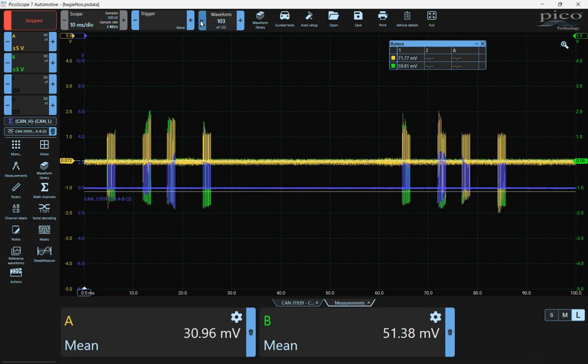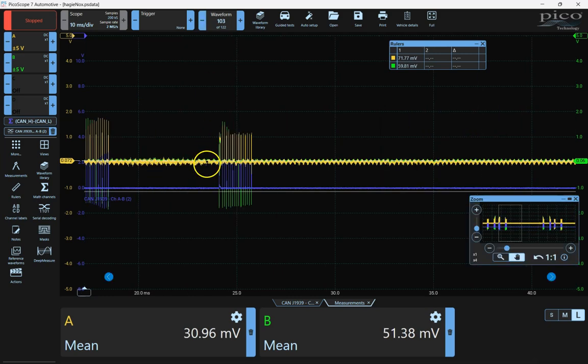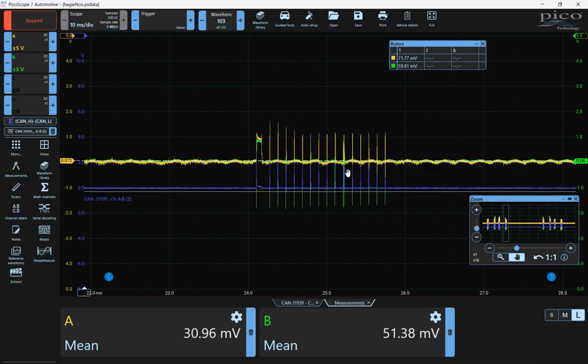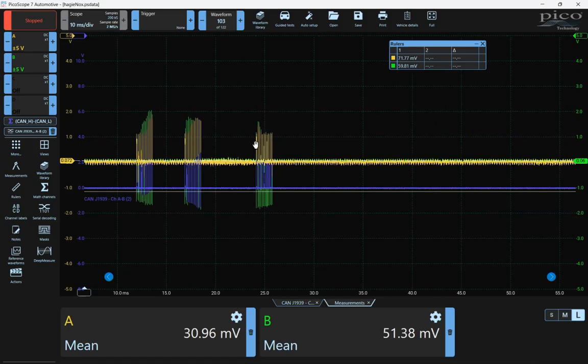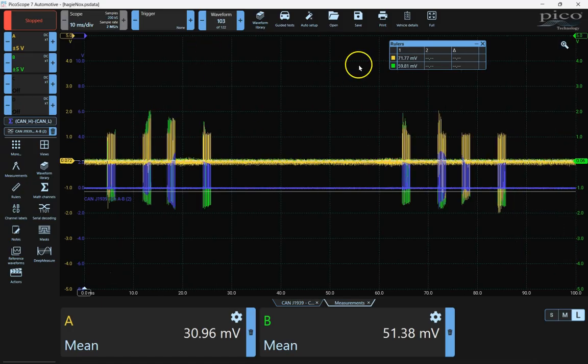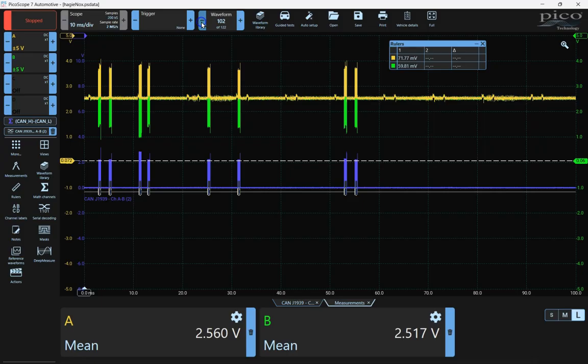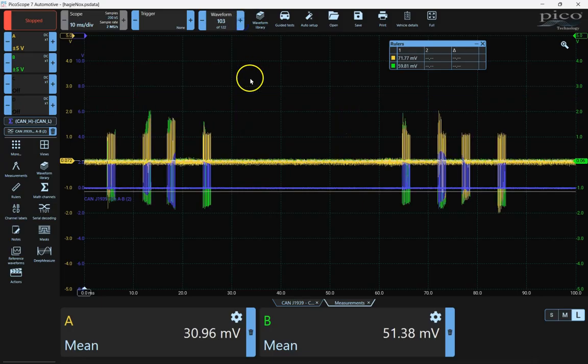This was a very short duration most times. You can see here we're trying to get that message out. The NOx sensor is not able to communicate. We can see that we got this issue. So because of that short to ground, and what I would have seen on my multimeter if I were just watching it and I had a peak hold, I would have maybe seen it flash briefly. This is not very long that this is shorted to ground.